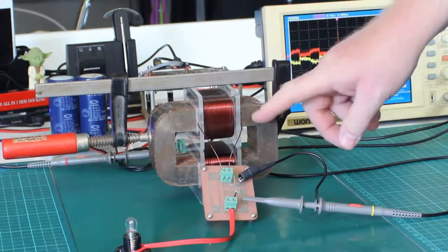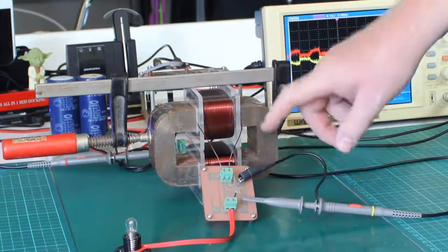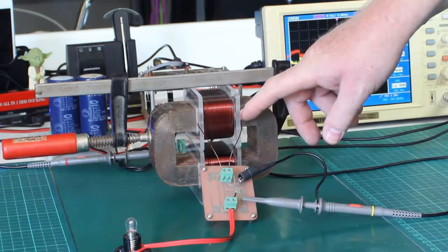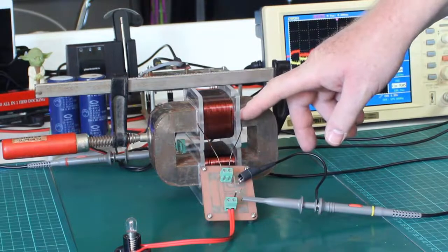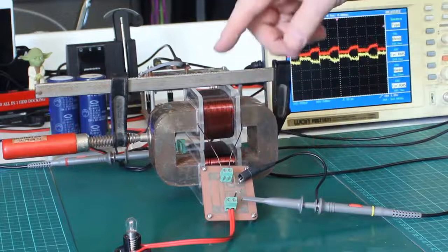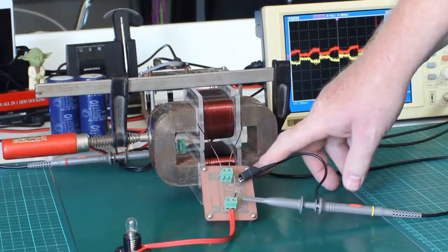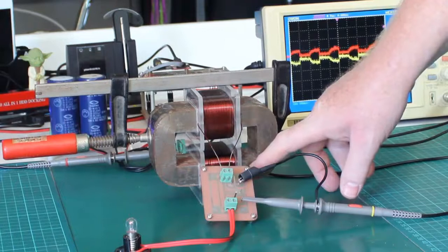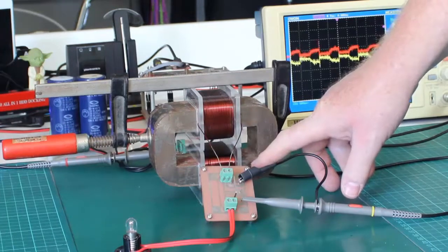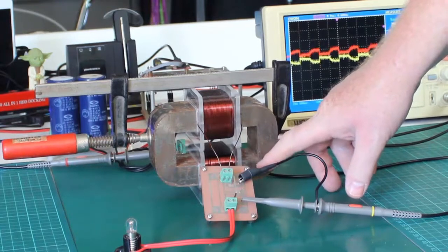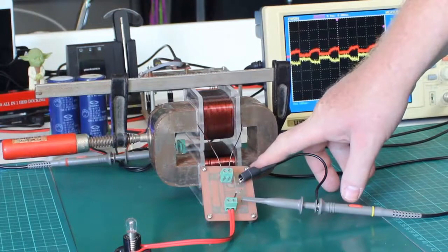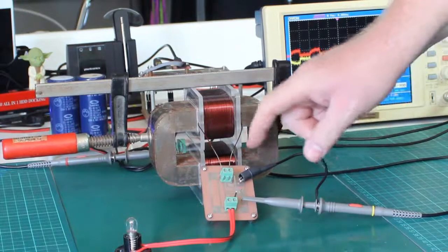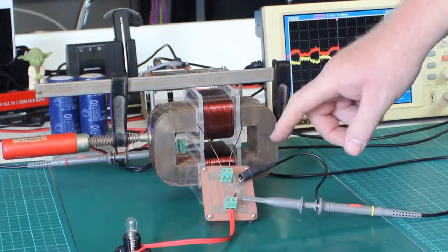Now when the magnetic field changes in time, you've got to remember nearly all of the magnetic field will stay in the core, that the core is in some cases many thousands of times easier to travel for magnetic flux than it is to travel through the air, because the core will have a permeability, and the permeability basically means that the core will allow for flux very, very much easier by that factor. So say for example we've got a core with a permeability of 5,000. That means it's 5,000 times easier for the flux of the bottom coil to travel through that core than it is through the air.